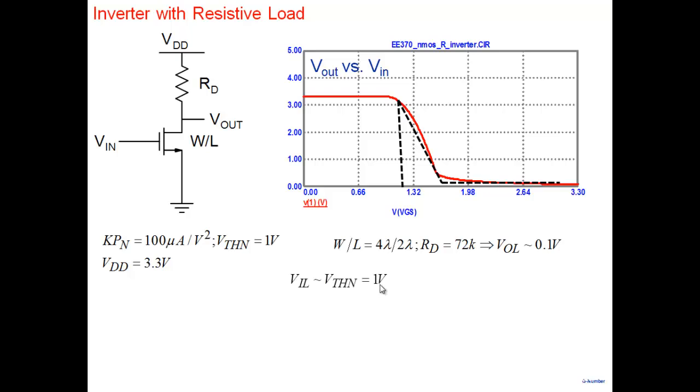All right. If you want, as I said, I'll leave it for the homework. Find this point -1, and if you do that accurate calculation, it says VIL is 1.07. It doesn't happen at the threshold point. It happens a little afterwards, obviously, but it's 1.07. So we are not too bad by saying that VIL occurs at the threshold point, 1 volt.